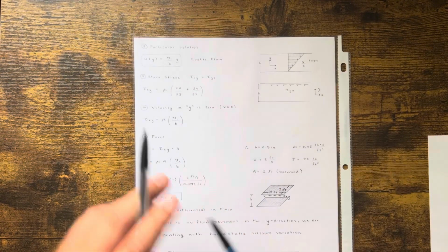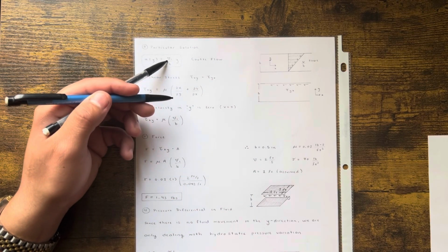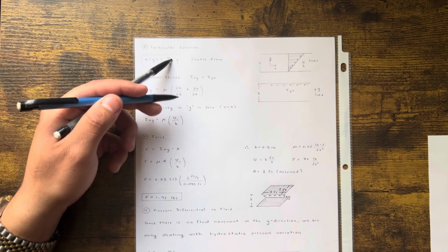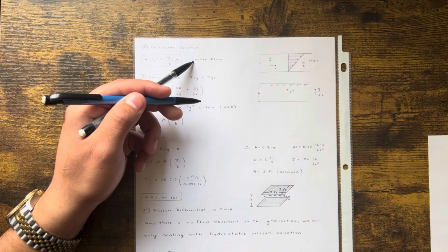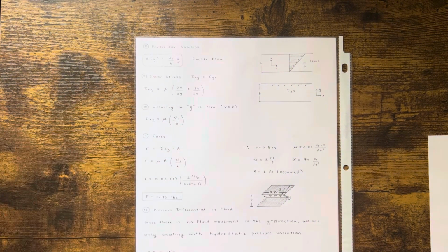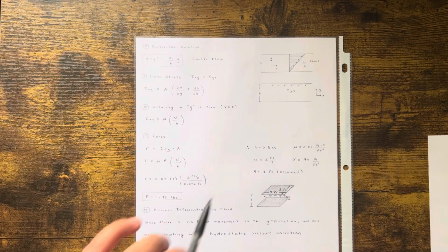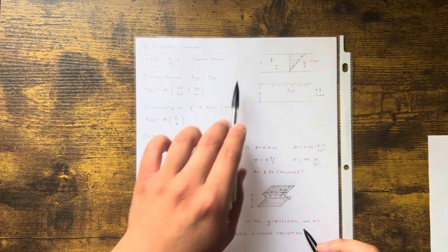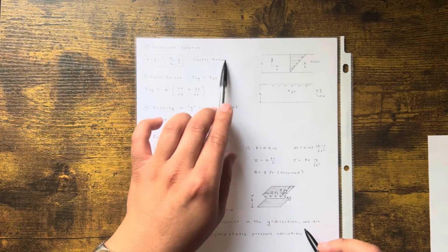So now that I found my particular function, I just plugged in my c1. This is c1, right, u1 over b, and this was just u of y. This was my general solution, but after applying the boundary conditions, now I have my particular solution. And this is called the Couette flow. I don't understand these foreign names, right? Who knows? It doesn't matter. All that matters is that this flow is simply for a plate that's moving while the bottom one's staying still. And this scenario does describe a lot of real life problems, right?